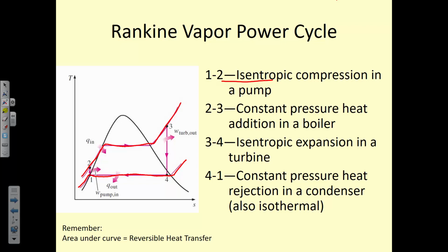And this provides a better explanation of why we use the temperature when we're looking up liquids, when we're making the compressed liquid approximation, rather than looking it up by pressure. Because we're looking at a significant pressure change here, but it's a pretty minimal temperature change.